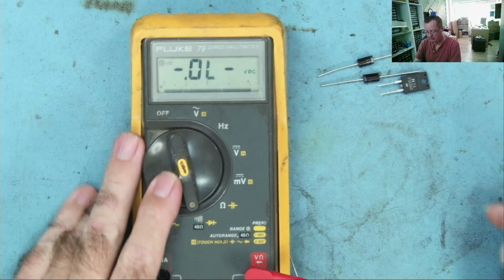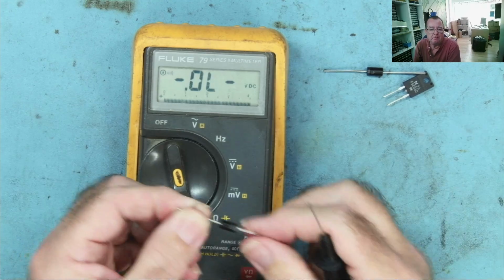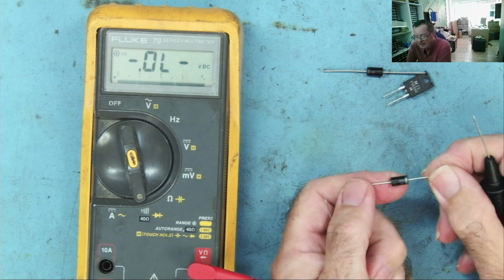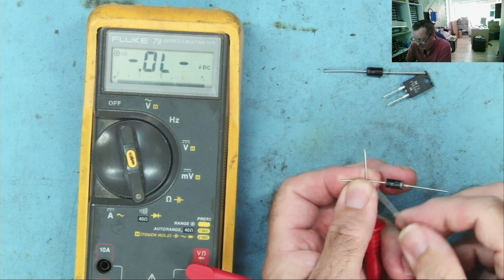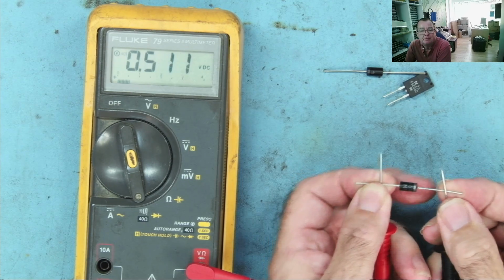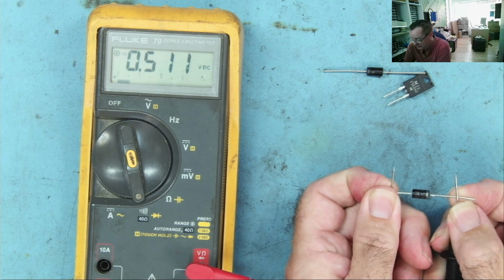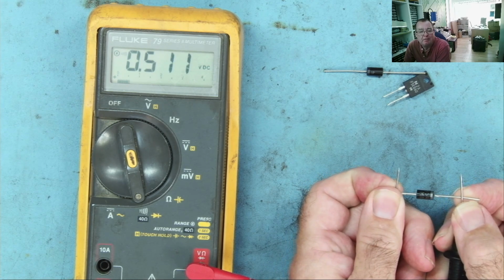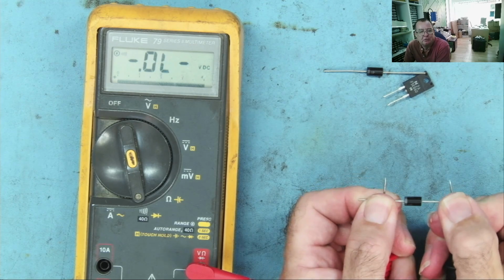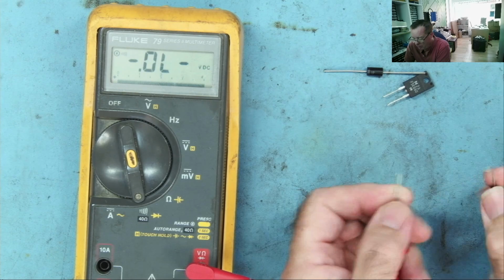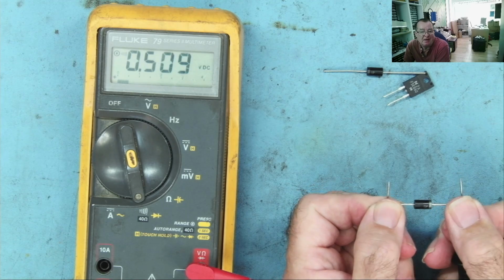Let's look at testing some components in diode mode with the component out of circuit. Let's just start with the most simple things then. So this is a rectifier diode, silicon diode, and we put the meter probe across with the black lead to the stripe. So this is the positive one, the red, to the anode, and it conducts. And we can see the voltage drop there across the diode, 0.511. And if we reverse it, this will not conduct. So that is a good diode. If it reads open in both directions or short, which will be in both directions, then it's a faulty diode.